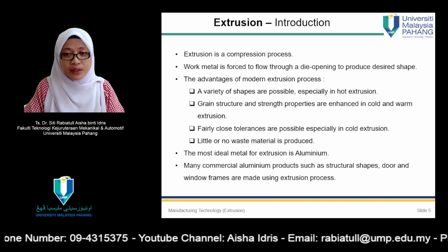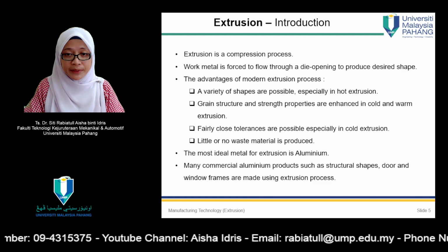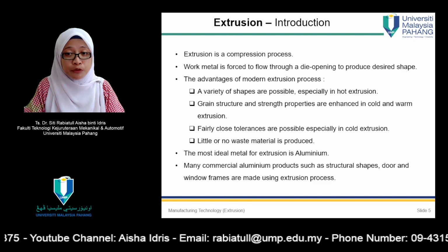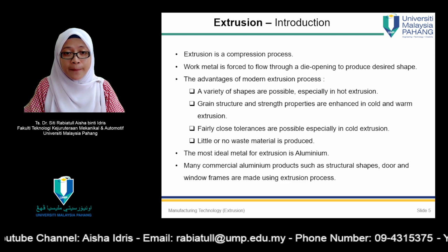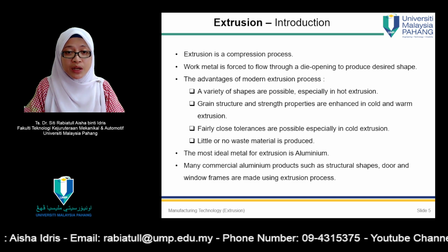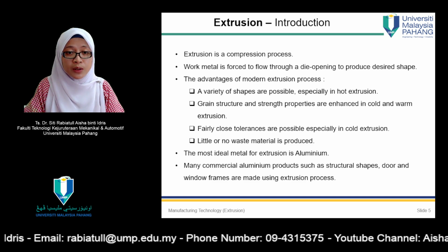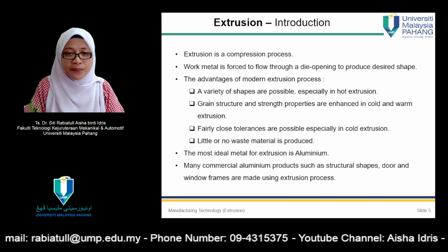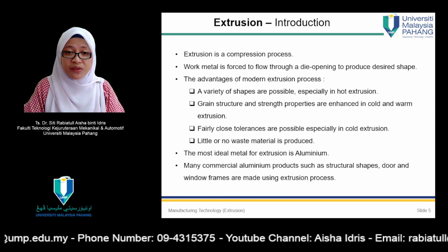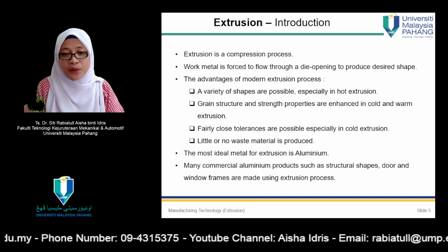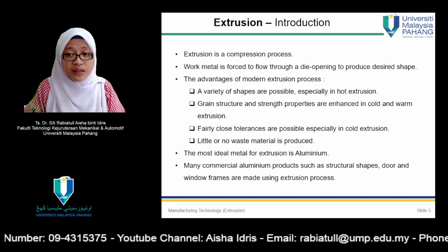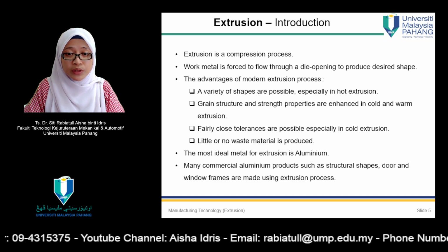So extrusion is actually a compression process. Metal is forced to flow through a die opening to produce the desired shape. The advantages of extrusion include that we can produce various shapes of final product, especially through hot extrusion, because there's heat involved and that makes it easier for us to form the product. Other than that, grain structure and strength properties are enhanced in cold and warm extrusion.